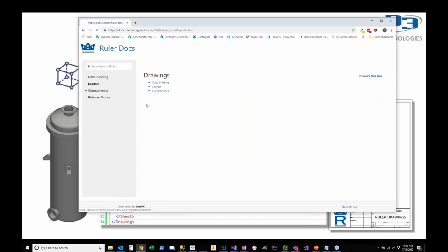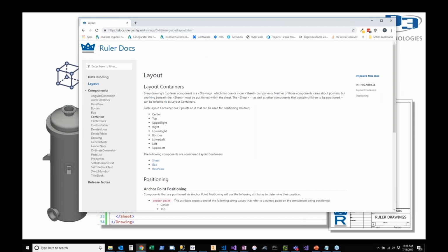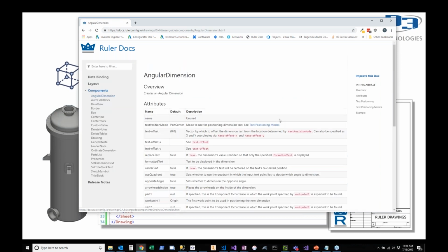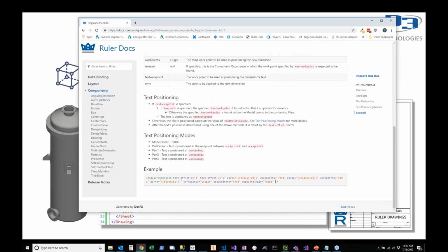At the end of the day, we've got 1, 2, 3 vertical dimension objects that can create any and all of these, depending on the configuration that's sent over to it. It looks at the model data and says, I'm going to go create all these things. And so in just 34 lines of code with some white space between, I can take any compressed file and create what they call a sales sketch type, pre-buy type drawing, where it just gives overall dimensions on these locations. And it's very fast.